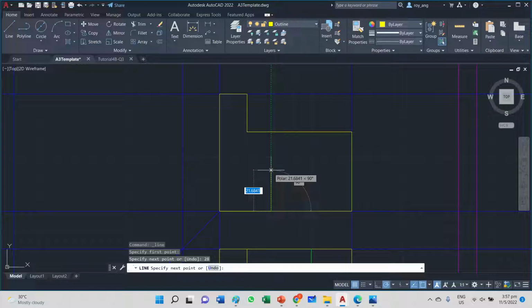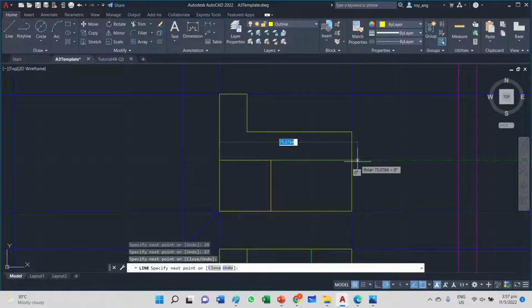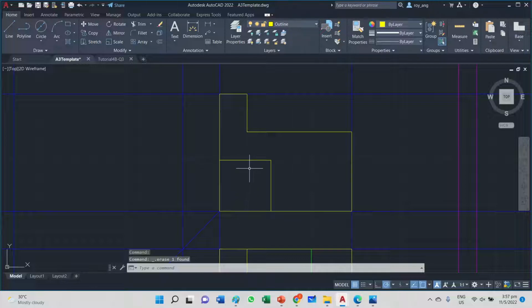And the next thing I'll do is mirror all the features. I want to be careful that I don't mirror excessively. I go across. Remember to delete away and select the object. Now, you see, if you do an offset, then you've got to do a trim, so it becomes pretty inefficient, and it can be quite annoying. Right click to accept, and the mirror point is here.